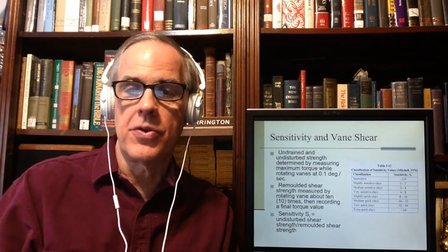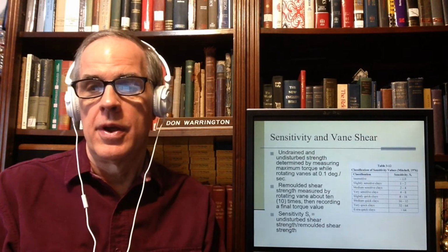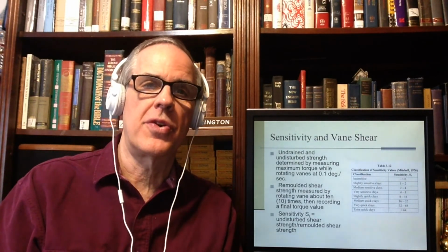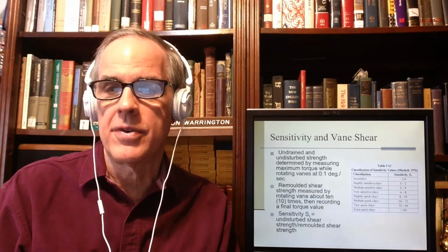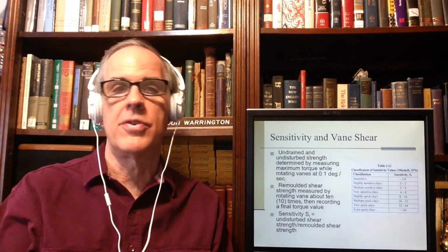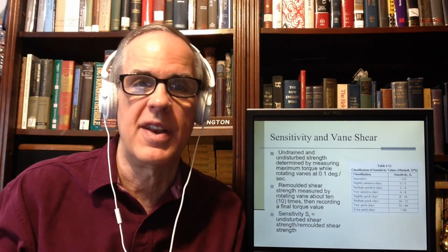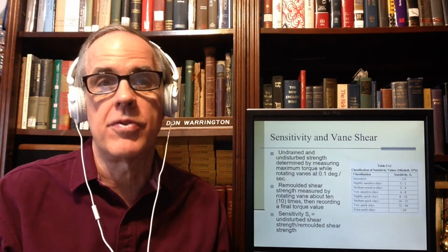When you remold it, you turn around and go back and get another value for another torque. If the two torques are pretty close, you don't have a very sensitive clay. If you go back and the clay just turns to mush, and you don't get any torque or very little torque, then you've got a very sensitive clay. This is sort of a quick summary of tests, and it can be very useful.